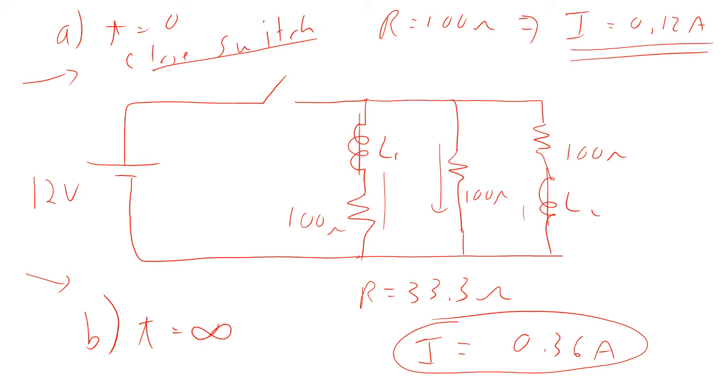One example of this also is, for example, if you have an electric motor. Remember, an electric motor is a coil of wires, and you've got current flowing through it, and then you unplug it from the wall. Then what happens is you're going to get a spark because this inductance tries to keep current flowing for a while afterwards. And so as the current continues to flow, you end up with a huge voltage and then a spark.